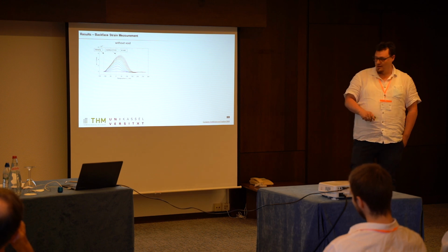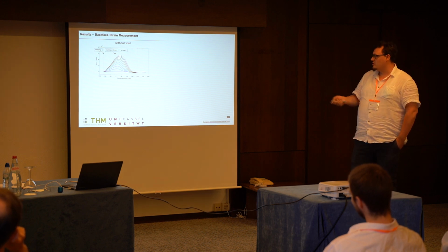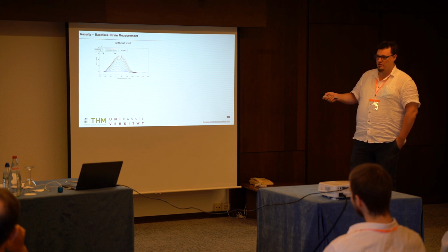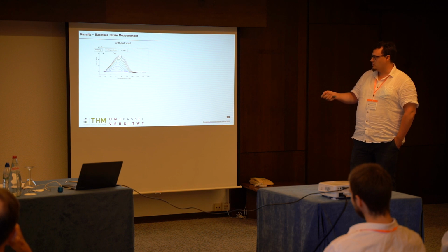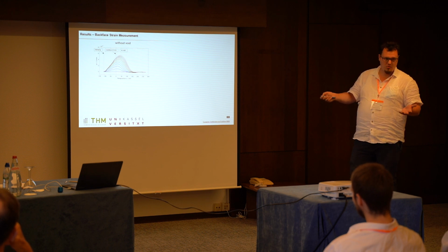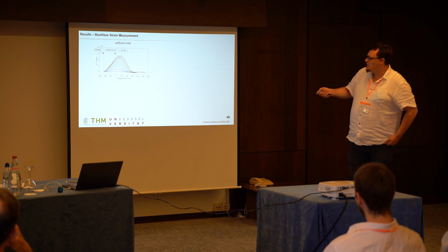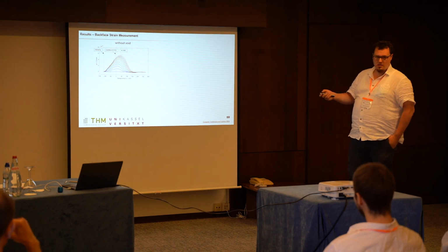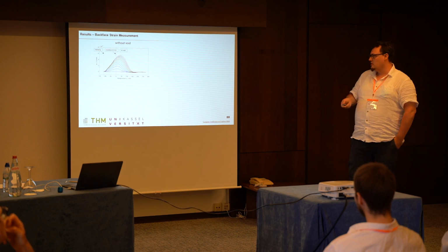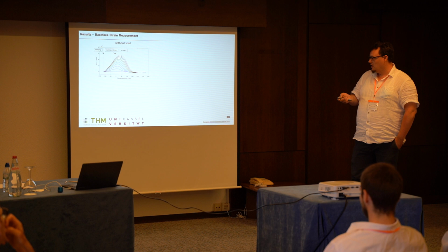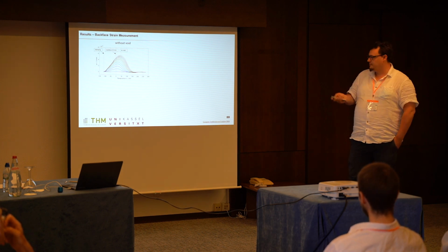Now the results, first of the backface strain measurement. In this diagram you see the second derivative of the deflection curve plotted over fiber position. This is proportional to the bending moment and our fiber strain. In the middle, the dotted line is the crack tip, the initial crack tip of the adhesive layer. In front is the clamping. That's the example for the specimen without void.